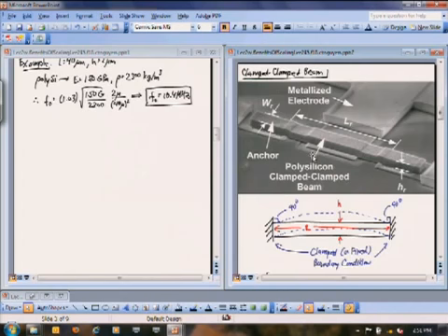Anytime you have a force in phase with mechanical motion, that's a stiffness. And it turns out this is a negative stiffness. That's kind of interesting because there are a lot of EEs right now trying to implement negative capacitors for energy purposes. Turns out that this negative stiffness is equal to a negative capacitor. So in a MEMS technology, we already have a negative capacitor that can be used to interesting effect in actual circuits. And one effect you're seeing right here is that negative stiffness is subtracting from the mechanical stiffness, taking us from this 10.4 megahertz to what we actually measure, which is 8.5 megahertz.